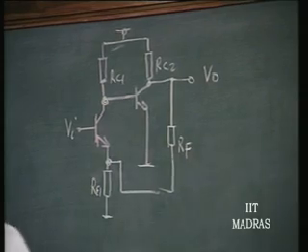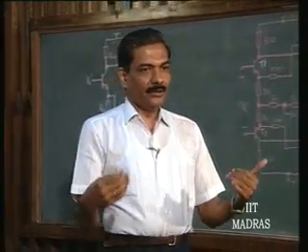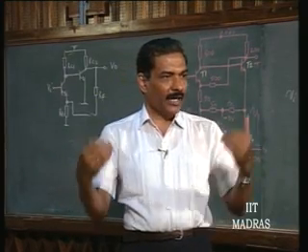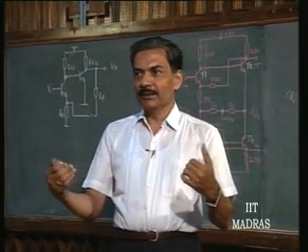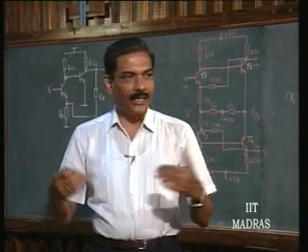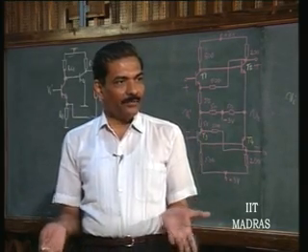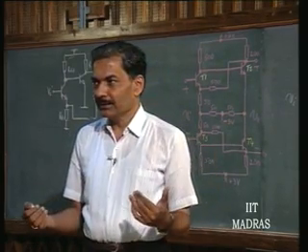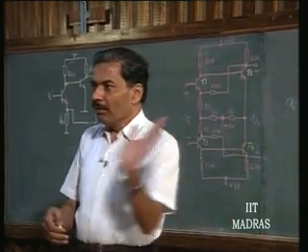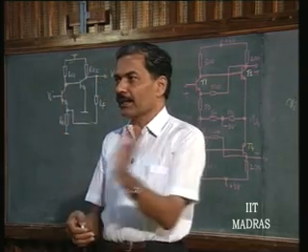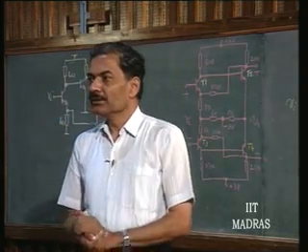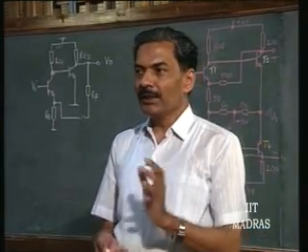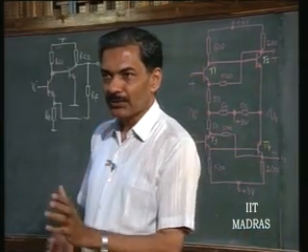H feedback, it is easy to use H parameters in the analysis, because the H parameters of the amplifier and the H parameters of the feedback can be easily evaluated and added together, and the modified parameters will be the G parameters, and obviously all the G parameters except the forward transfer parameter will go towards 0. It is an idealization towards a voltage controlled voltage source.